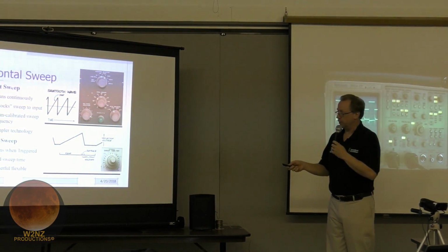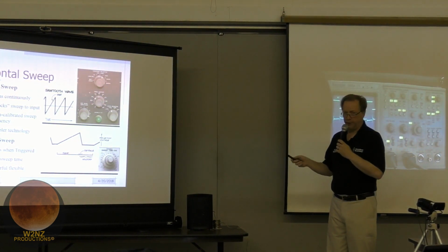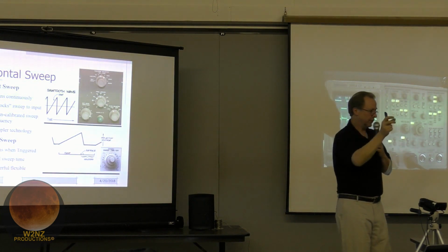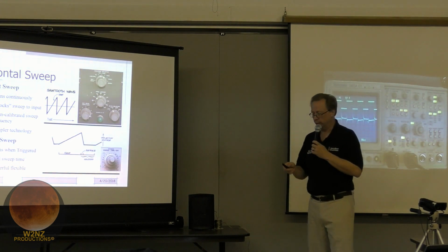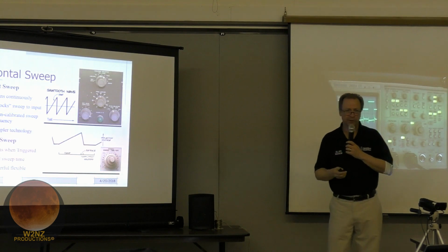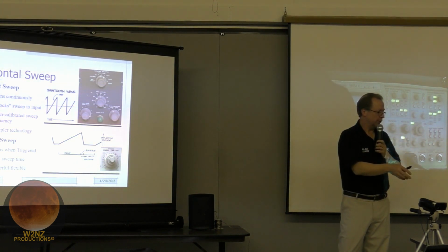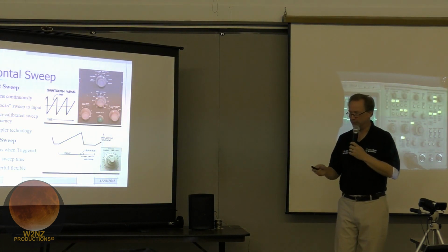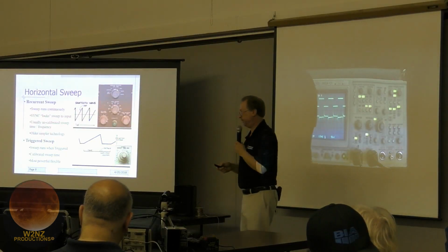And you can usually tell a recurrent sweep scope because you've got a frequency vernier as well as a range selector. You can say, I want to sweep at 1 kilohertz, and I can adjust the vernier to adjust that sweep speed. It's not calibrated, and it's very difficult to trigger with. We'll talk about trigger in a moment. I would say these days, there are so many lab-grade, engineering-grade oscilloscopes available that there's no excuse for you to be using a recurrent sweep scope anymore. Okay, you can pick up a real scope, I should say, a real analog scope, pretty inexpensively these days.